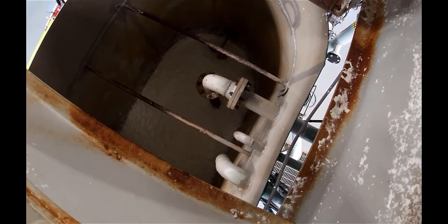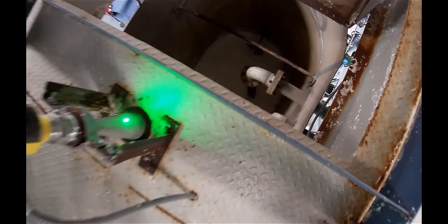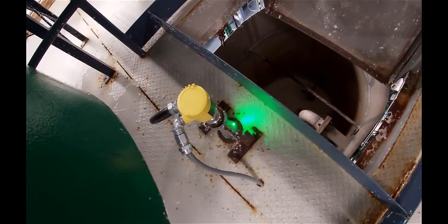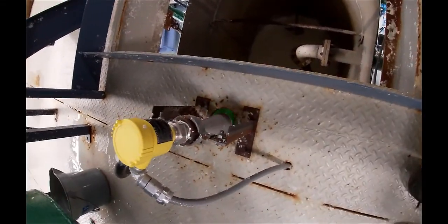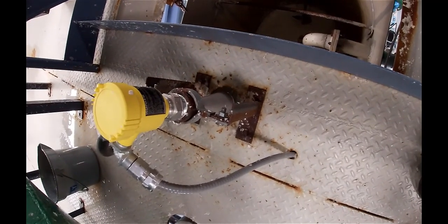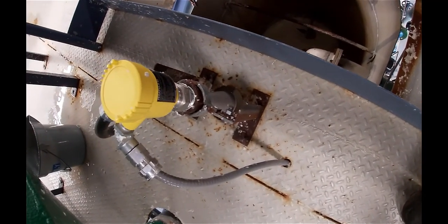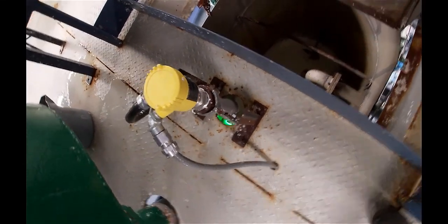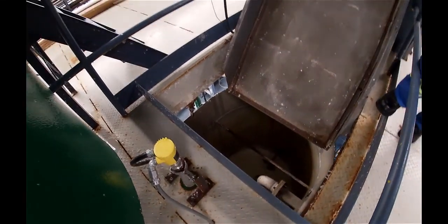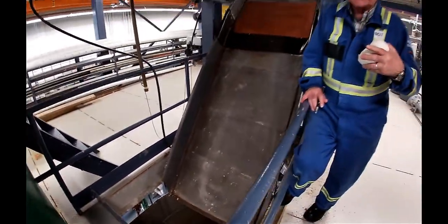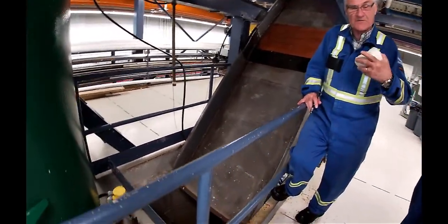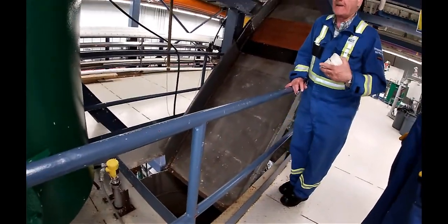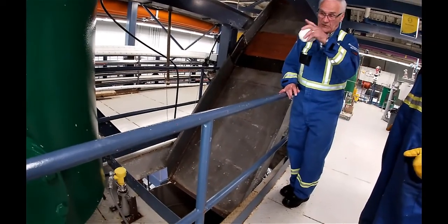Lastly, Ray, just come up a little bit. That right there is the radar level transmitter that was measuring the level in this stock tank. The sequential function chart would not open up the dump valve if there was insufficient room in there. It's basically interrogating it to make sure that the level is less than 1,500 US gallons, and then we've got room to dump that.